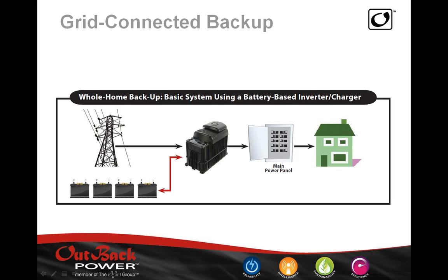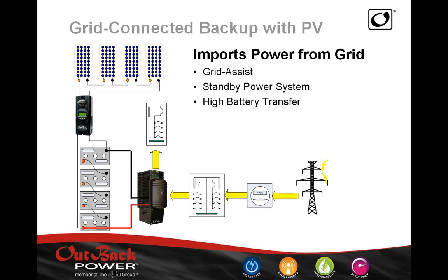But I just want to reemphasize again here that the inverter will automatically transfer from the batteries once it sees the grid fail. And that transfer time is completely programmable. You can tell the inverter to do it within 0 cycles or 240 cycles, which on a 60 hertz line basically means from 0 to 4 seconds, and that's completely programmable.